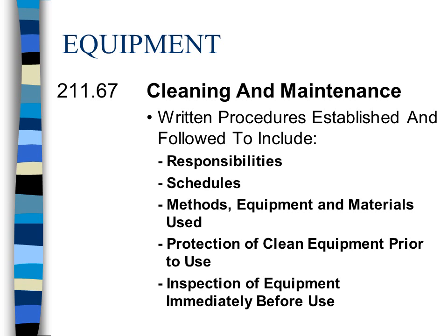It deals with the inspection of the equipment immediately before use. We refer back to our delivery tickets. Whether you're filling a liquid oxygen reservoir or a nitrogen dewar, there are specific steps that need to be taken. You inspect the equipment prior to fill to make sure that that piece of equipment will not only accept the fill, but is acceptable to use.